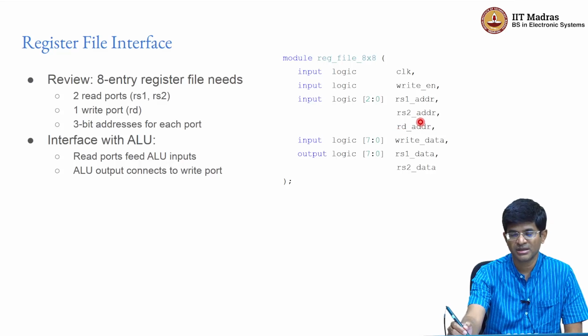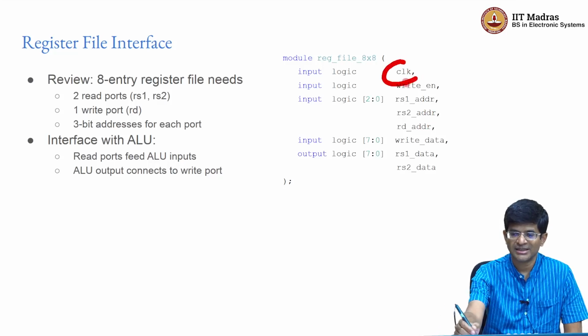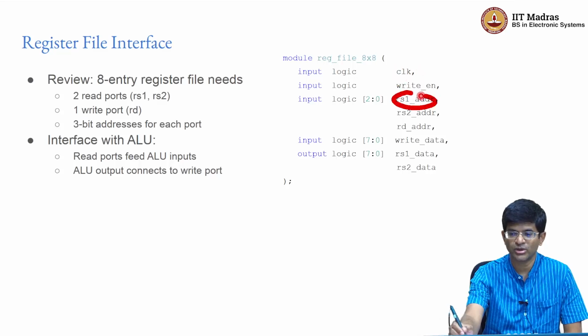What that would mean is both the multiplexers for the reading are essentially reading from the same source register, which is perfectly fine. They are also writing back into the same register, and all that means is that the write operation anyway happens at the next clock edge, right? So it doesn't interfere with whatever value I read out now. So the value that I read out now and the value that I write back at the end of the clock cycle could very well be different.